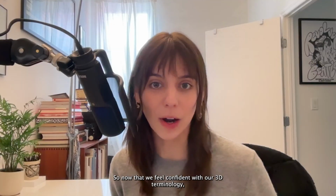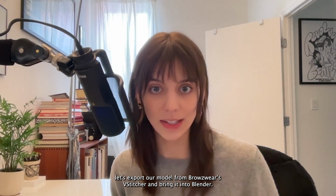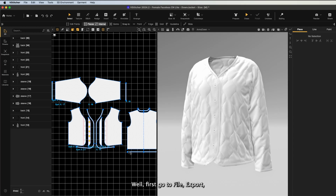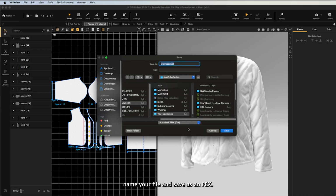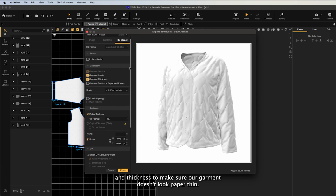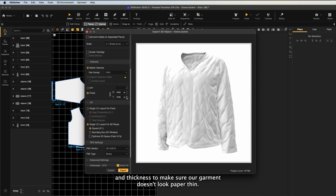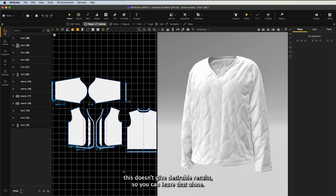So now that we feel confident with our 3D terminology, let's export our model from Browzwear's VStitcher and bring it into Blender. We'll first go to File, Export, name your file, and save as an FBX. I like to include garment inside and thickness to make sure our garment doesn't look paper thin. Under the UV settings, turn on single UV layout for all pieces. You might be tempted to turn on optimized 2D space for better texel density, but I often find that this doesn't give desirable results, so you can leave that alone.